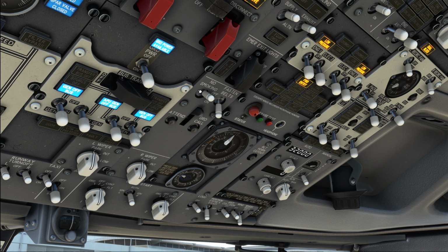So, just as a small background explanation, the no smoking sign is always on in the cabin. The switch does not have any actual effect. But the switch has 3 positions, and we are using them as a reminder. So with the switch in the off position, we assume that our cabin is not ready, so the passengers are still standing up.